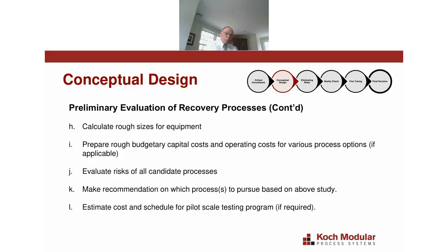And we also know at this point in time if we need to do some pilot testing or not. I would say in most cases, we don't need to do the pilot testing for distillation because we usually have in our database enough vapor liquid equilibrium data to allow us to confidently model the process.